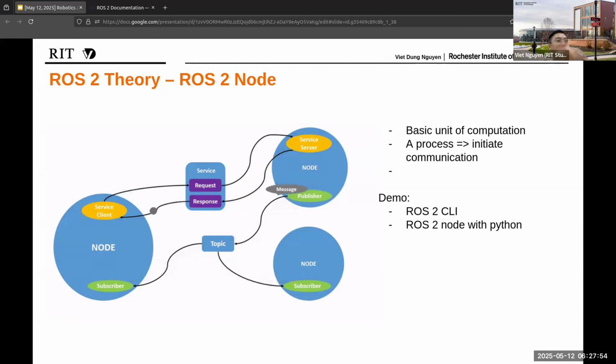robots, for example, sending back real-time sensor data, if you send back sensor data directly to the subscriber, the laptop, for example, it might process the data sequentially, I guess. But for the purpose of parallelism and distributed computing, I think it's just sending to a common gateway, which is known as a topic, and then the laptop will just grab whatever information is staying inside the topic. I think that might be one reason why, which is parallelism, that is making all these paradigms and structures more efficient. Yeah. And then there's also service, but I'll talk about that later.